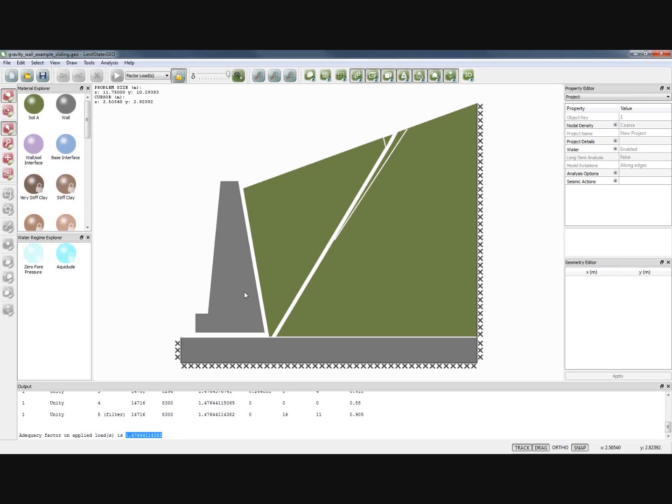You'll see in the animation this wall is moving sideways, also moving upwards. That's due to modeling the friction on the base of the wall in plastic analysis. Friction is modeled as dilation, so in the animation you actually see that manifesting as dilation, but essentially it gives you the same effect for friction in most cases that we're looking at.